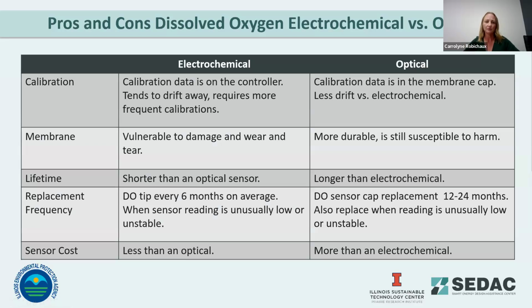Okay, we talked about, well, Sean mentioned electrochemical dissolved oxygen probes and optical dissolved oxygen probes. Electrochemical probes are kind of tricky. They haven't been used probably for over a decade, and now they're coming back. So I'll have to do more research into why we're starting to see them again. Optical probes, that's going to be your luminescent dissolved oxygen. That is an industry standard methodology. Every manufacturer is doing it the same. Technology is great, it's solid, and it works out well for 99% of the applications.